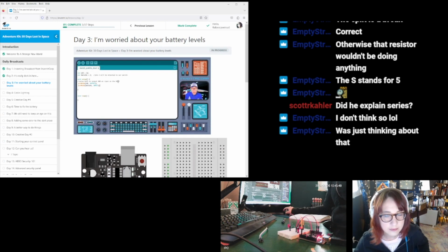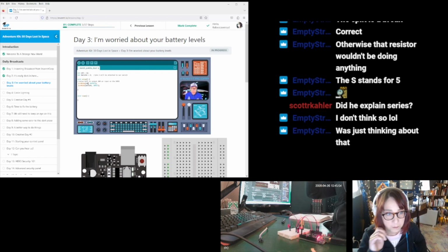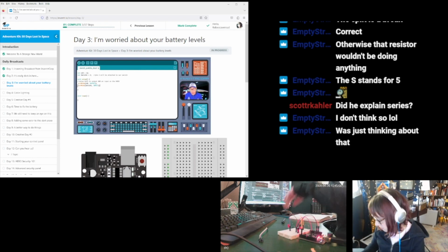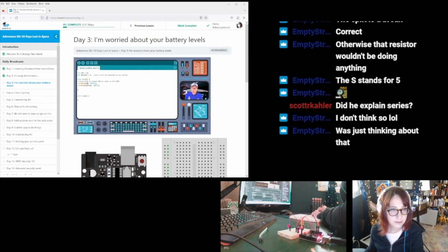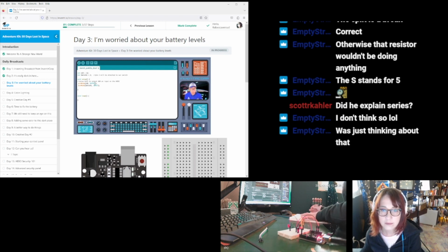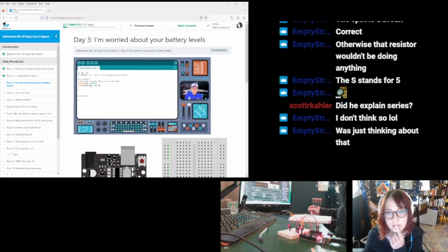We are now once again using pin mode. And in the first of these two statements, you'll notice that pin mode is very familiar to us. It's just like we used it last time. We're taking LED, which is 12, and we're setting its function to be an output, so that when we command it, we can cause LED, or 12, to be either high or low. In contrast, we're going to use pin mode to make switch have a function of an input.